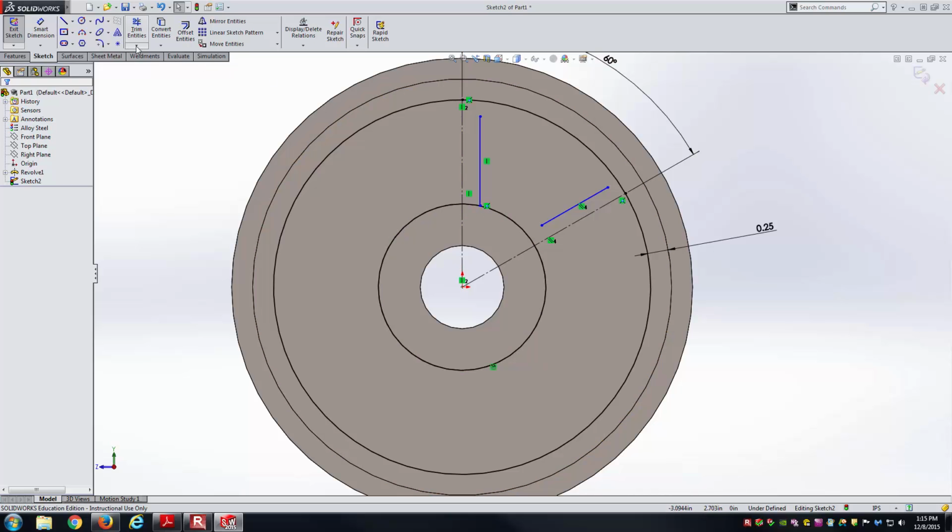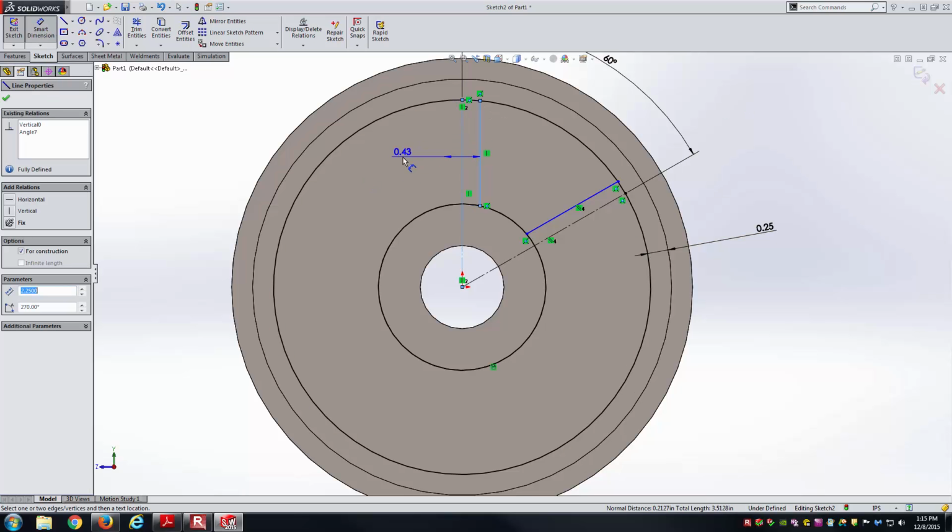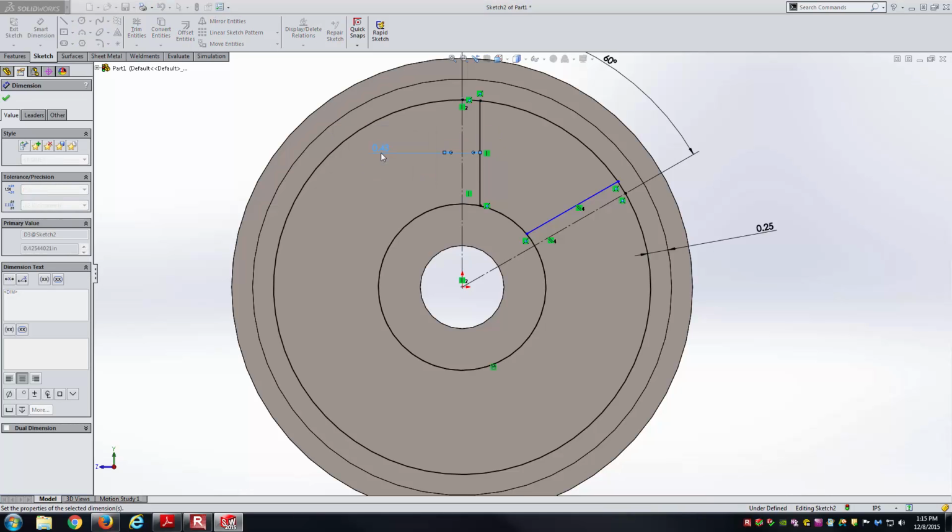Or what I can also do is go right under trim entities as extend entities, and so here just selecting near the ends of the lines, have them extend until they hit the next entity in its path. Now for the dimension for the 1/4 inch spoke width, and so there it is. Again, you've got the ability to watch the extension lines, whether it's going to be kind of a radius style dimension or the overall width in this case. So it's 0.25 here.